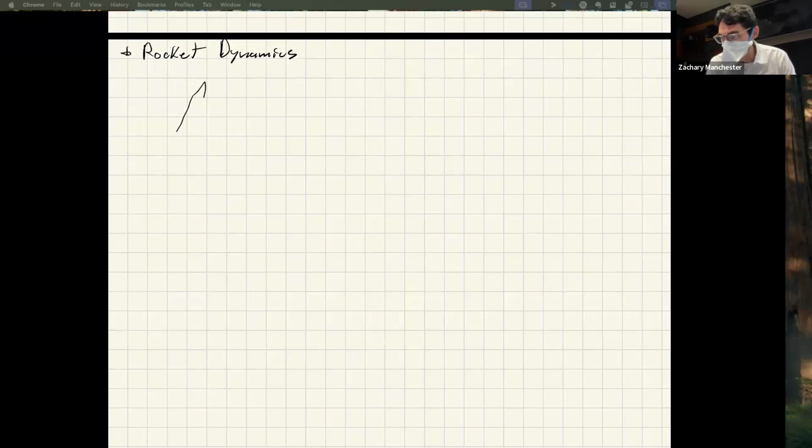So when we talk about it, it's not actually F equals MA because the M is time varying. So it's actually F equals dP/dt, where P is the momentum. And you've got an M dot term in there basically, right? So remember, force is the derivative of momentum, right? So it's really F equals M dot V plus M V dot. That's really what's going on, right? And you have that very much in this case. So that's one area where this is a little different.